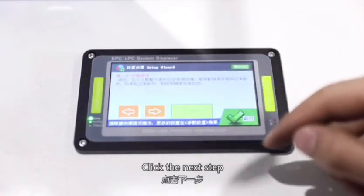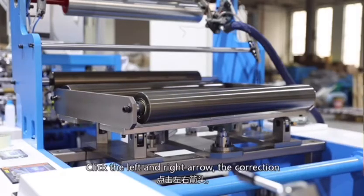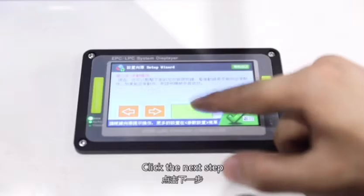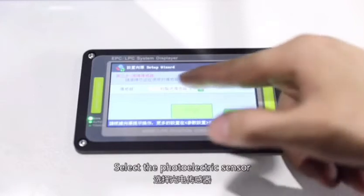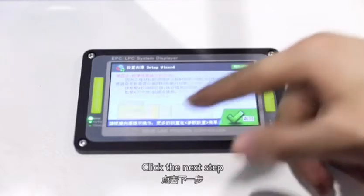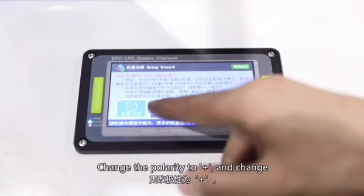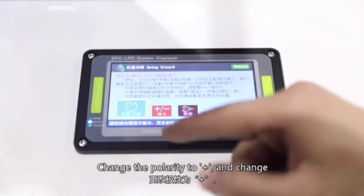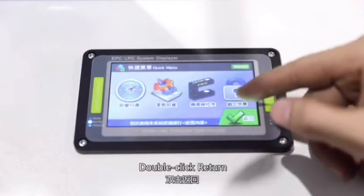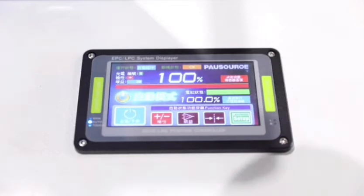Click the next step. Click the left and right arrow. Correction device can swing between the normal left and right. Click the next step. Select the photoelectric sensor. Click the next step. Click the next step. Change to automatic mode. Change the polarity to plus and change the gain value to 20. Double click return. Automatic deviation correction system setting is complete.